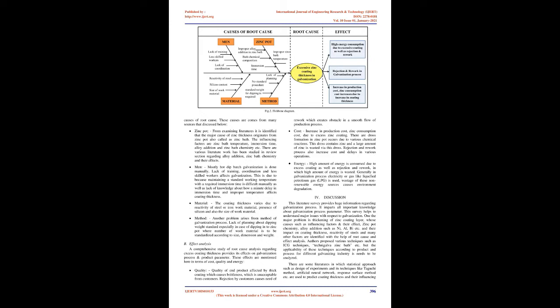Sanjeev Kumar Shukla, Anup Kumar Sadhukan and Parthapratim Gupta, 2017, used artificial neural network, ANN, model to predict galvanizing zinc coating thickness by developing an offline model. Sensitivity analysis is done on Taguchi orthogonal array technique. 6 factors are considered with the help of the ANN model, such as bath temperature, Al content, wiping gas flow rate, holding time, distance between nozzle and strip, and residence time. Authors conclude that ANN is a powerful tool to identify coating thickness.